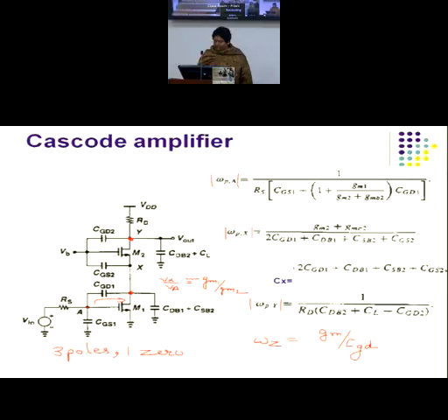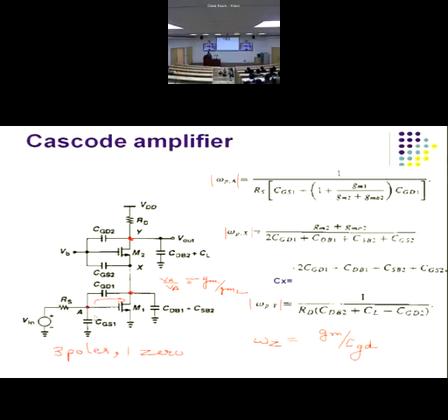I can announce it. Now cascode amplifier, as I said, we would mainly focus on the intuitive analysis. How to estimate poles and zeros using intuitive analysis. So as I said, roughly every node leads to a pole. And then identify the feed forward path to get the expression for the zero transmission. So this we were discussing last time. So we have how many nodes? Node A, node X and node Y. This R can be an active load, can be a passive load. Accordingly, you have to take the expression.